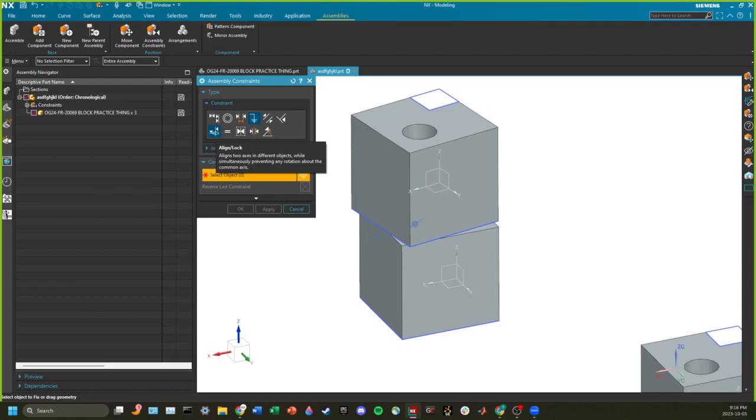Axial, if you have a hydraulic or something where it's pushing, coming out like that, and it's sliding along a shaft, and you don't want rotation for whatever reason. Let's say you had like a punch and you're lining it up with something else, you'd use a line lock so that it just slides in that direction.